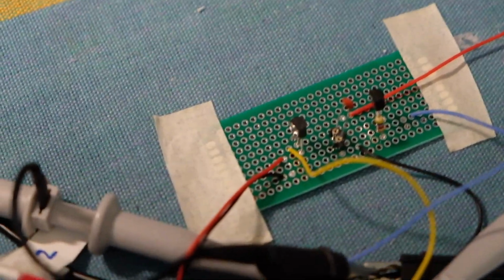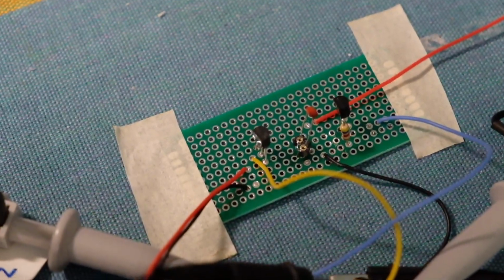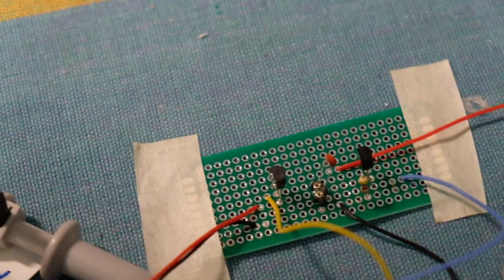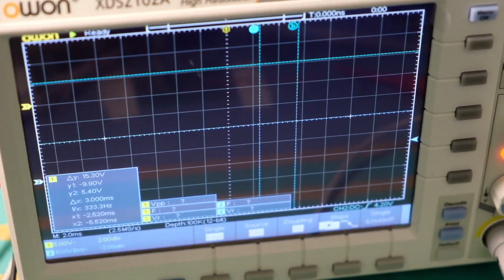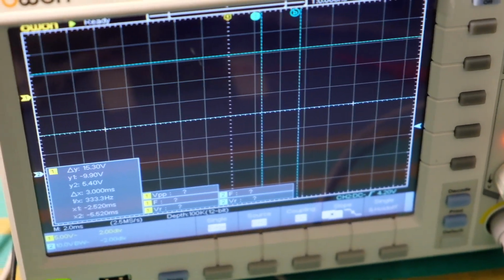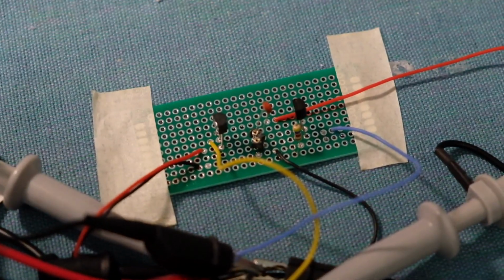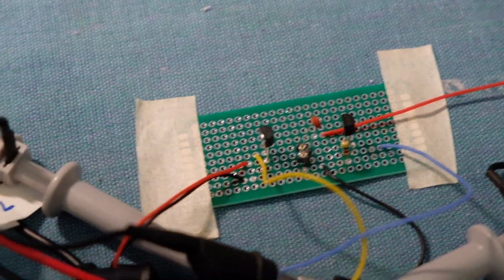And here's the board, the circuit board, which I soldered these components onto, and all I need is a scope to measure the sawtooth waveform that's going to come out, and the reset. I'll look at those two signals, and I will synchronize the oscilloscope on the reset signal, which is a very nice signal to sync on.